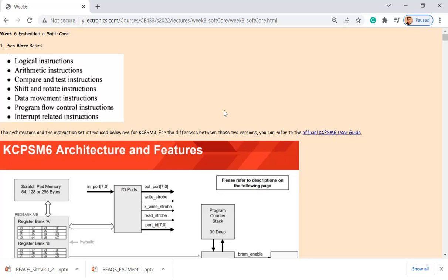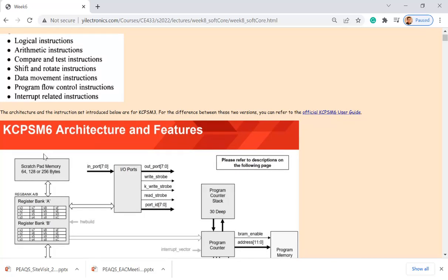It's going to be a different instruction set, which means the instruction set has corresponding hardware, because you must have the hardware, like an adder, so you can add something in assembly. When you are adding something, it's actually using the adder's functional block to do that computation. So, for example, this PicoBlaze is actually a microcontroller. It has all the peripherals and has a CPU core. When you instantiate that PicoBlaze, called KCPSM6, in your Vivado environment, it's actually placing a microcontroller on the FPGA.